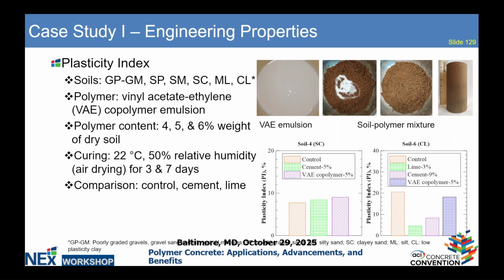Usually, we won't have a lot of issues. However, if you have clays, which is a very plastic material, sometimes it's very difficult to mix it in the field. So that's the parameter we want to see: how adding polymers or other stabilizers will change the plasticity index.